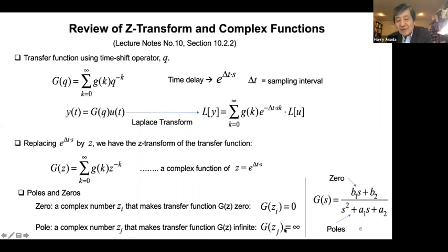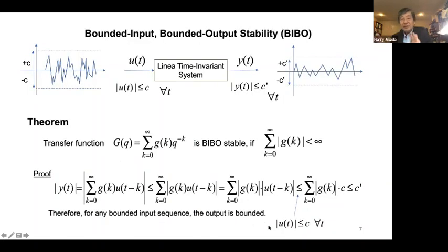So if this goes to infinity, that is a pole, right? This agrees with the earlier definition: set the denominator to 0, and that's something divided by 0, so G shoots up. That's how the pole is defined. That definition is a little bit broader, so let's use that.